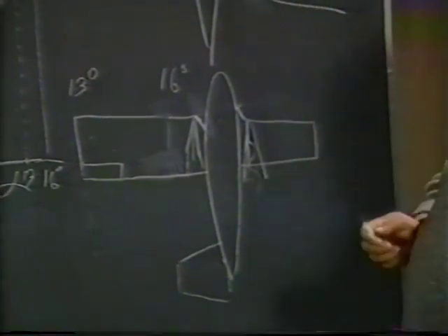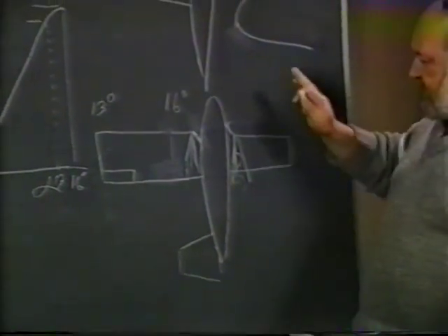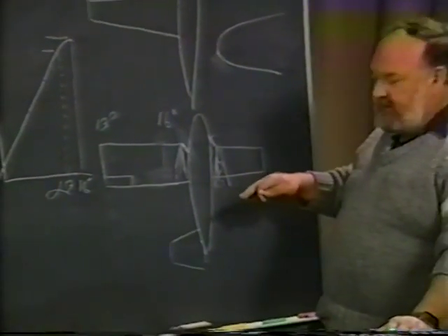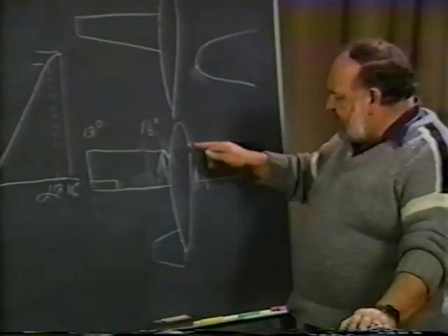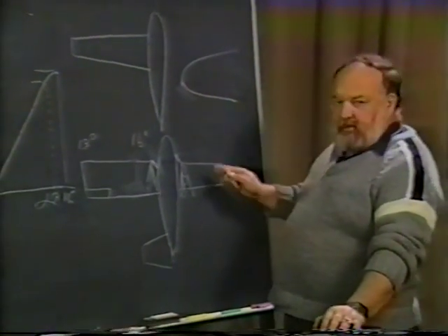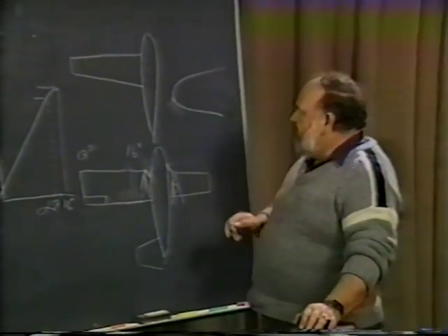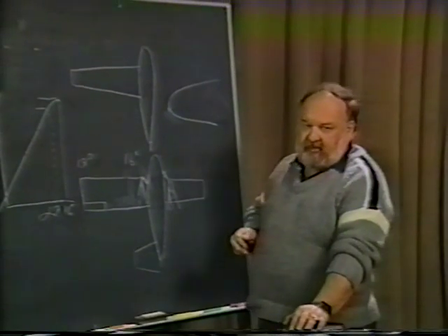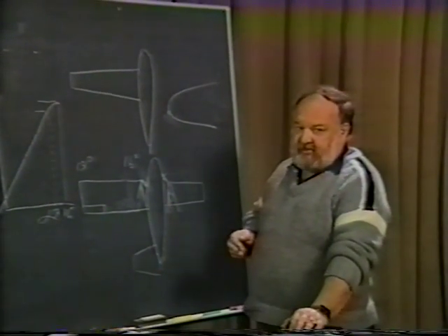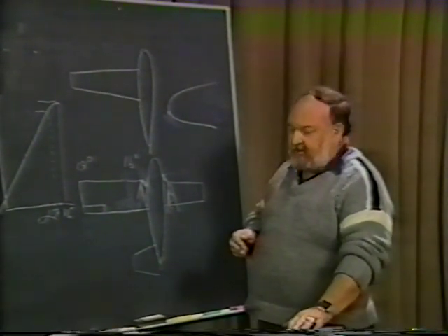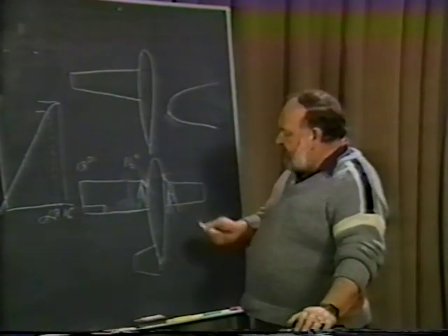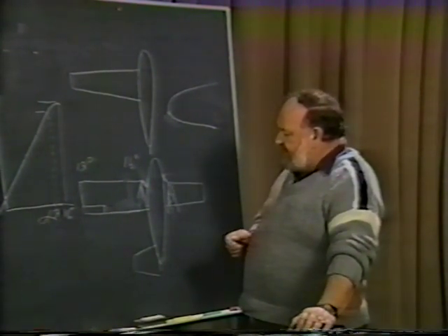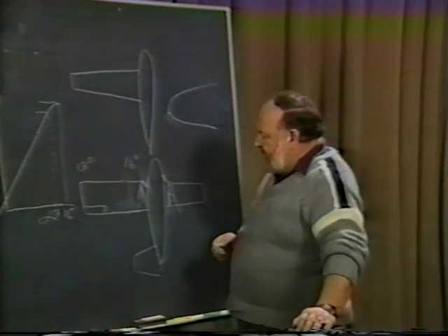It's a little bit like you have with the stall strip here, except that once you level out, once you get cruising, this swept leading edge, whether it's swept forward or backwards, has no adverse effect, whereas if you put a sharp leading edge on your airfoil section itself, that's hurting you at cruise just as well as it helps you a little bit right near your stall. So this method works very nicely, has a very decided advantage all the way around.